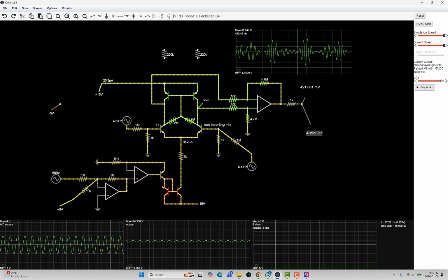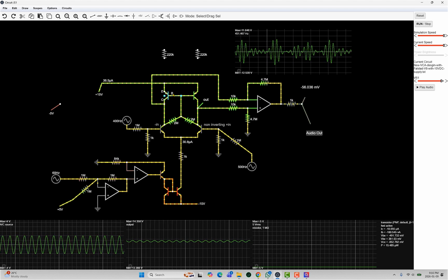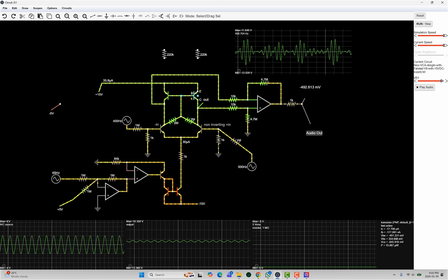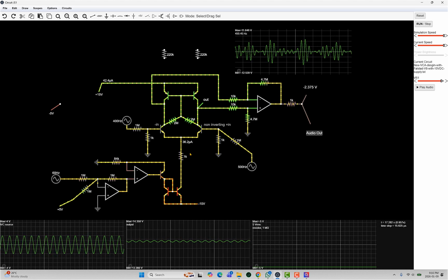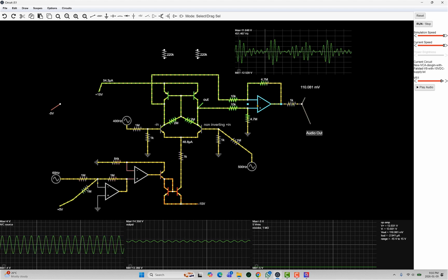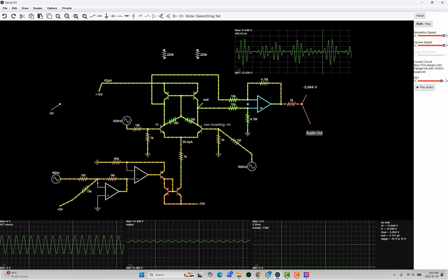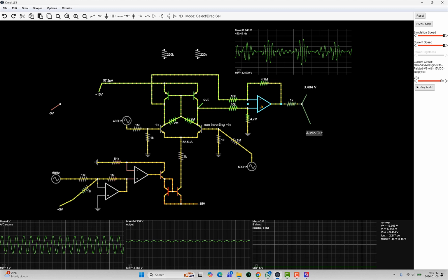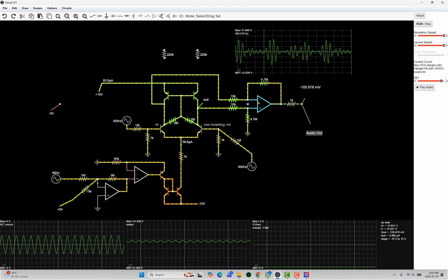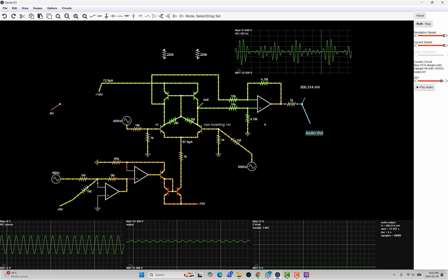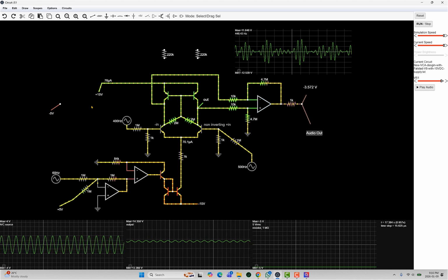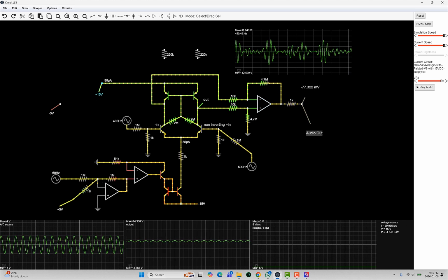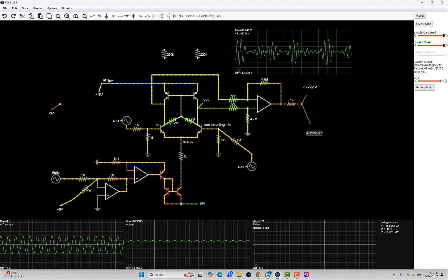So this probably is not as critical as these two up here, or these 4, 1, 2, 3, 4 transistors. This is just a garden variety op amp. Probably any TL072, I think, is what I would recommend, but you can try a lot of different ones, I suppose. And we have it at plus 15 and minus 15. That's probably a good starting point.